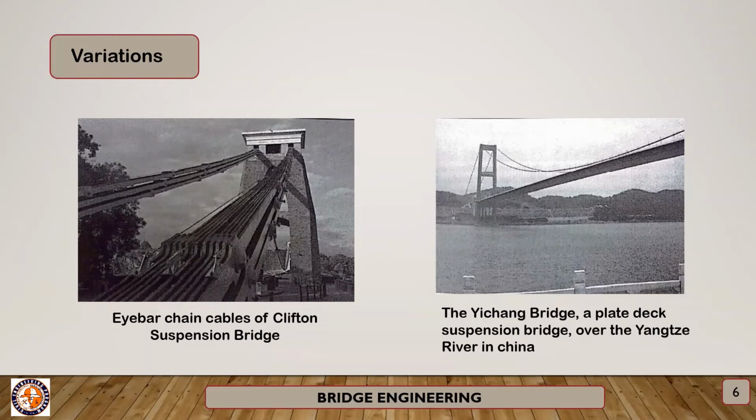In an underspan suspension bridge, the main cables hang entirely below the bridge deck but are still anchored into the ground in a similar way to the conventional type. Very few bridges of this nature have been built as the deck is inherently less stable than when suspended below the cables. Here are the examples.